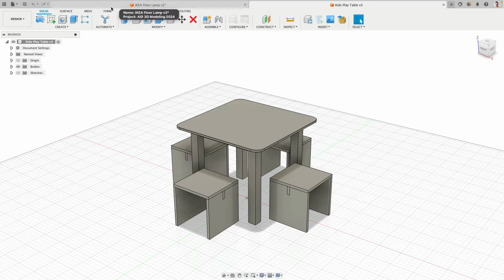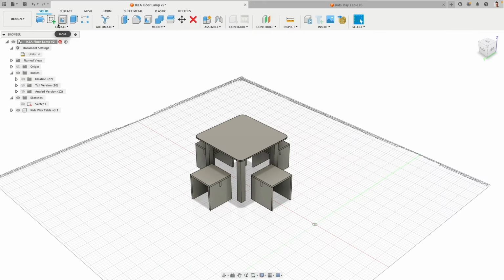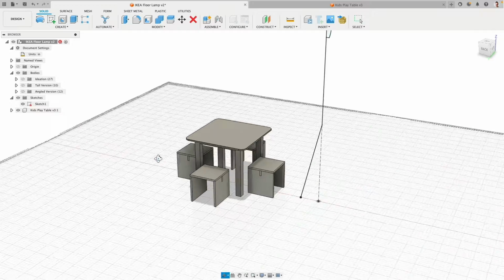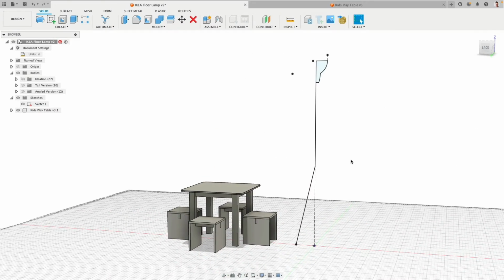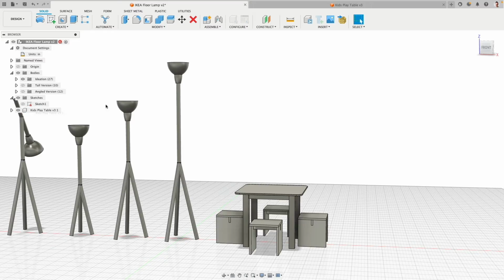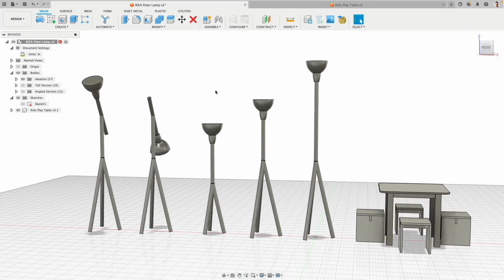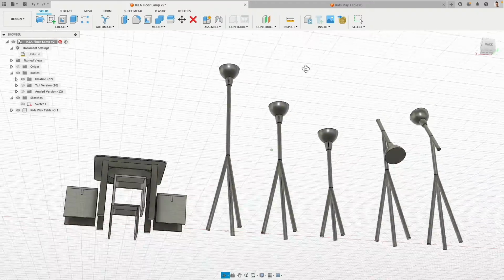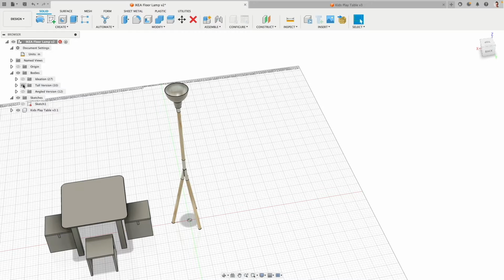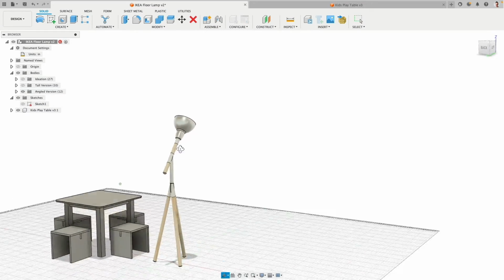The way I would start, and what I will show in this tutorial, is by starting with a new design and bringing an existing design into this file, so I can use it kind of like a 3D blueprint to create my sketch for the floor lamp. I can explore and verify dimensions and then use direct modeling to create different configurations very quickly with basic shapes. Then through this tutorial, I will show you how we make copies and refine those.